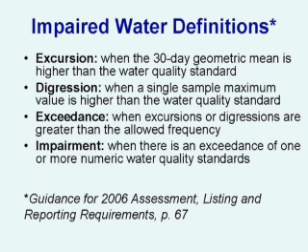Conclusions about disinfection: chemical and UV disinfection can be defined as a function of wastewater quality and temperature. Those are the 2 main parameters that you look at in designing your system. Wastewater quality rapidly changes, but it's predictable. If you get enough data, you can predict how it's going to occur, and you're going to have to look at over-disinfecting, over-oxidizing, and over-dechlorinating, taking out the chlorine residual. The oxidant dose can be correlated with TRC and can be used then to control the dechlorination feed process. Disinfection byproducts are a function of dose and quality, and can be reduced through removal of precursors or using UV disinfection.